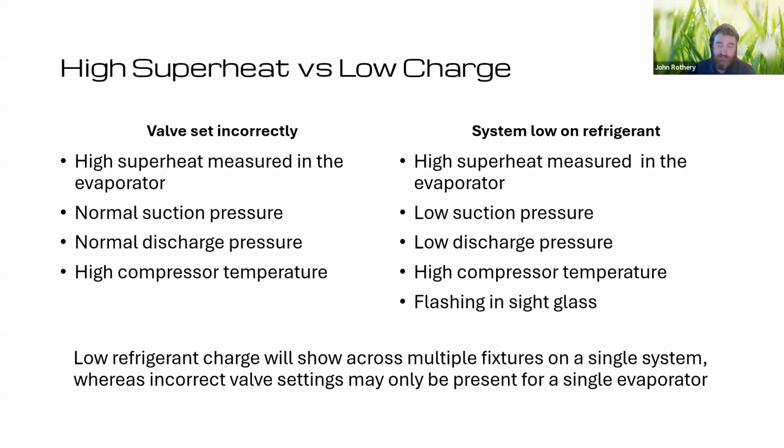An issue I have seen with regards to charge, if you're checking your vessel, is the RPRV, your flash gas valve. If you've had power cuts overnight, if it's a brief power cut, the valve starts driving closed, it comes back on, so the valve can actually go out of calibration. So it's always worth checking your valves are calibrated if you're getting oddities with fluctuating levels in your vessel. That's a good point.